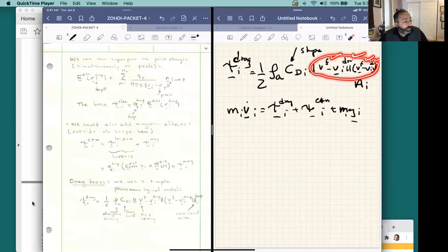It's quadratic, and it depends upon the absolute value and the direction of the fluid. It also depends upon what you're dropping inside. So depending upon what kind of droplet it is, you get a different drag coefficient. And it also depends upon the fluid itself. That's also a little nightmare, because the fluid, if it starts to change, which it could if we were doing a relatively complex analysis, this would lead to a coupled problem, meaning the object is changing the fluid that it's surrounding, and the fluid surrounding is changing the dynamics of the object.